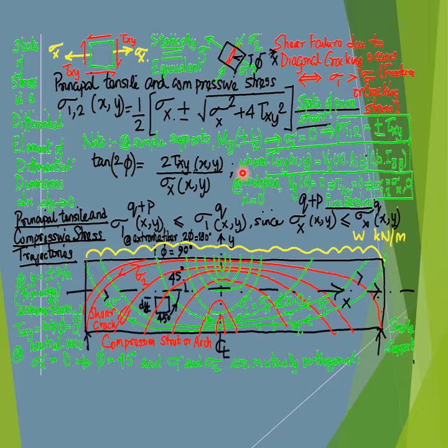Further, at the representative location of the midspan, that is defined by the x coordinate equal to 0, the shear force, that is the externally applied shear force denoted as V subscript y at x equal to 0, is 0 based on simple statics for a simply supported beam subjected to a uniformly distributed load.